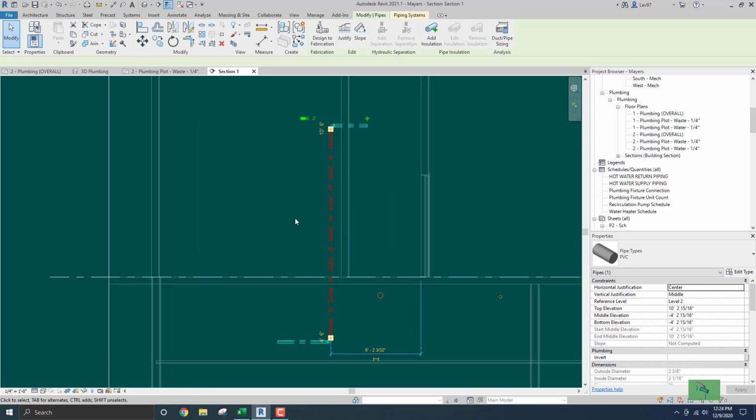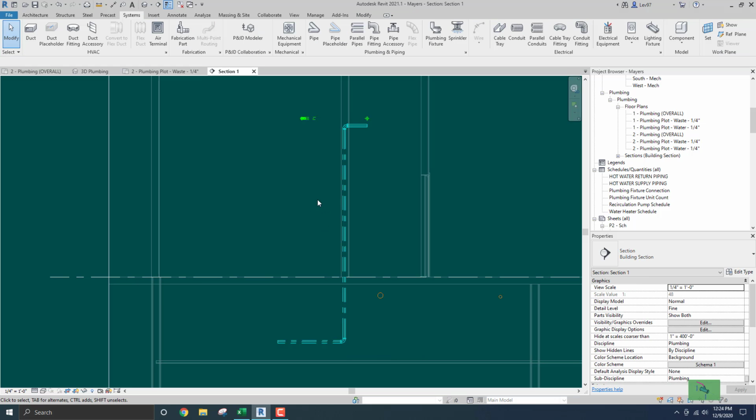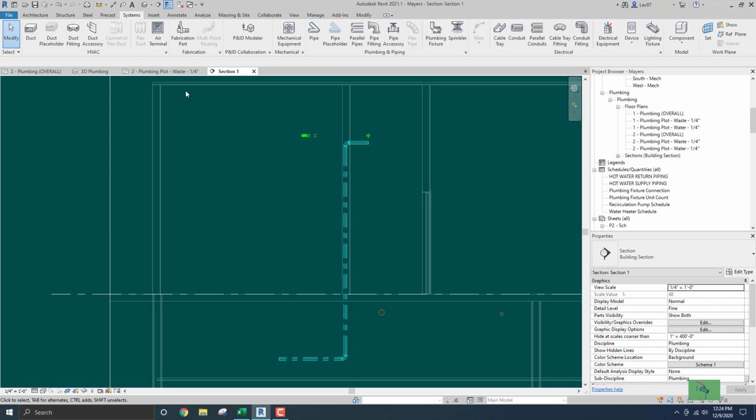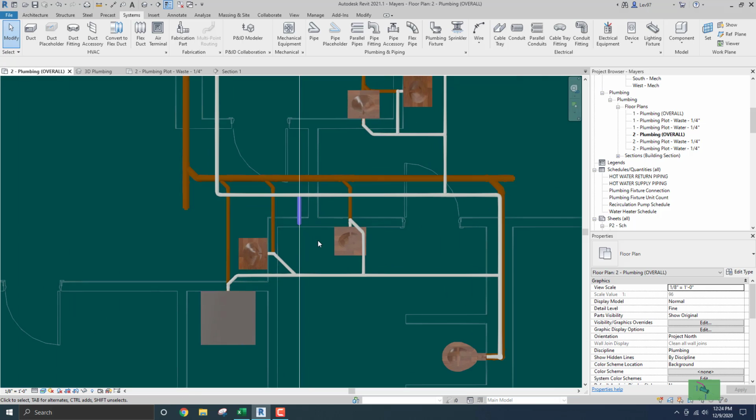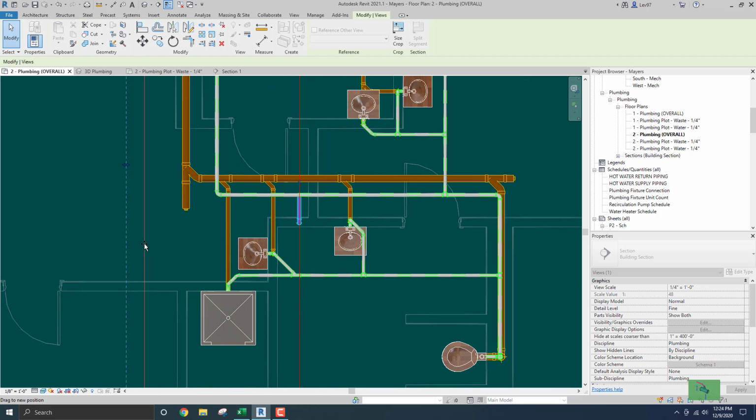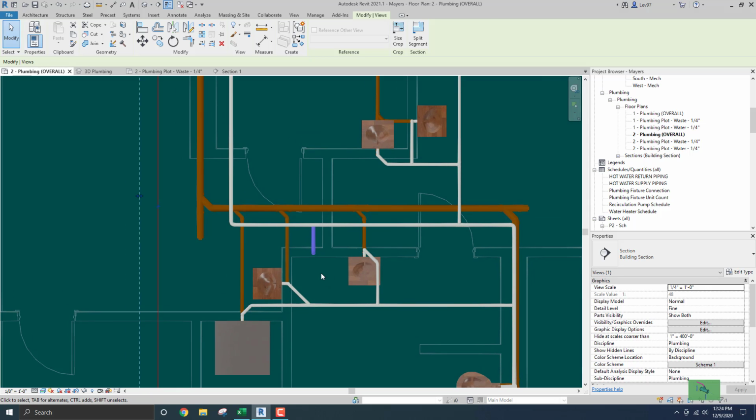And now we're going to put our pipe in the wall so we can come up nicely through the floor and into the wall space, or sometimes what you call a plumbing chase. If there's a lot of pipes going on and maybe you've got some duct going down into a shaft, it's usually called a plumbing chase when you're referring to plumbing, and it's called a shaft if it's more mechanical, okay? But in this case, it's just a wall. So we got 10'6".